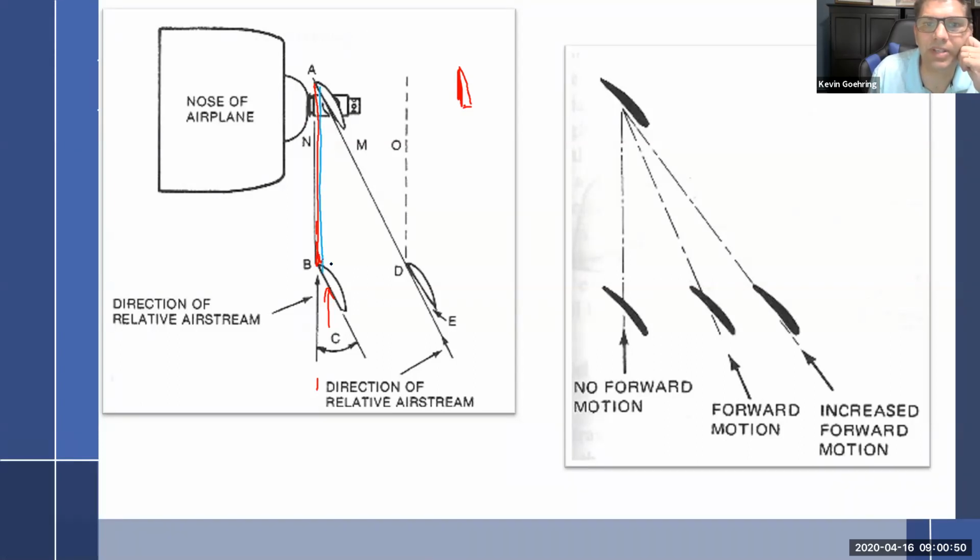Now this one, here's a triangle where this is the prop rotating. This is the forward speed of the aircraft. And now we're back to here. And that looks like the triangle we had in the last picture. Now we can actually get some sort of angle here and say, well, now we know how the blade should be fixed. And so at this speed, whatever this is from here to here, the prop is perfect. It's got a nice 3-degree angle of attack and oh, she's working sweet.